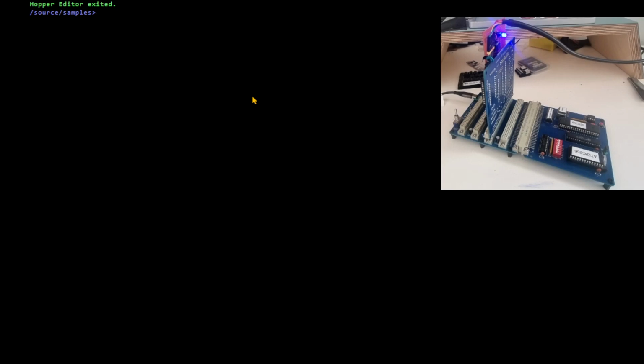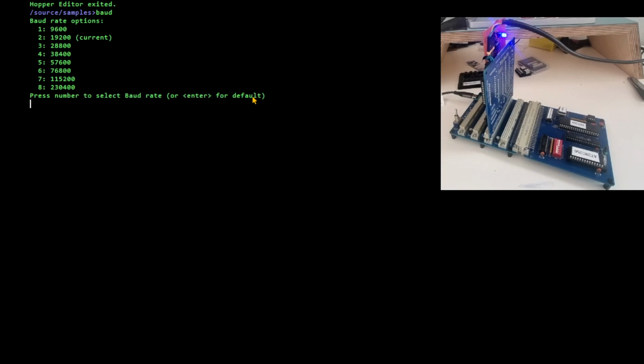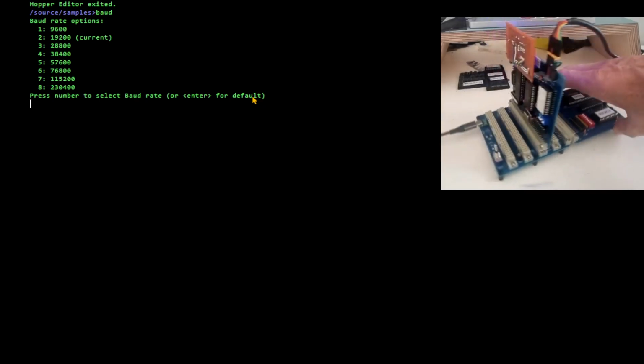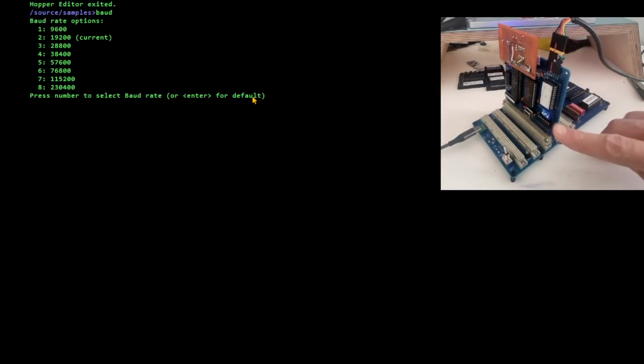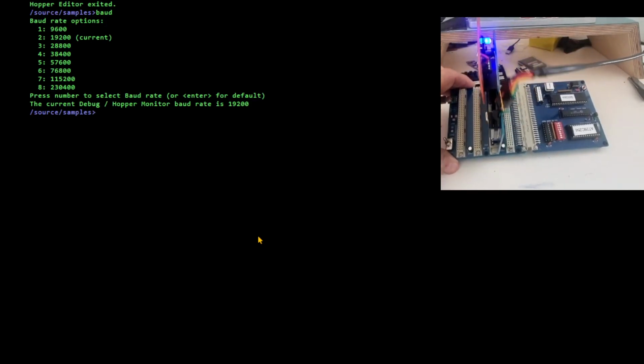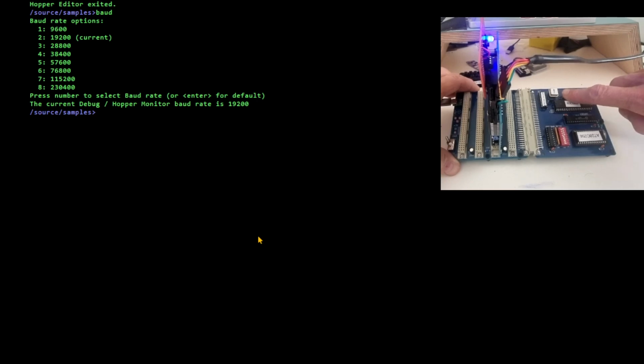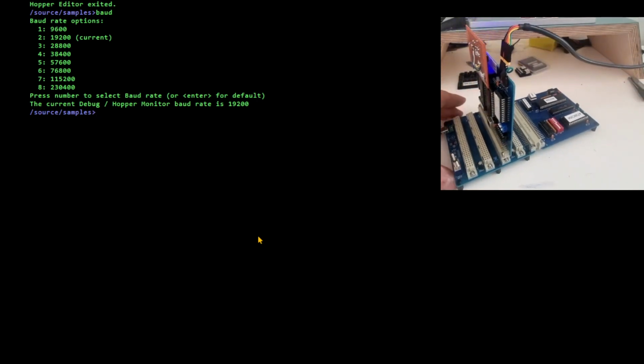Oh yeah, important: baud rate. We've got the board switched, with these dip switches here, the blue one, to 19200. If you're using the Hopper 8K BIOS you can use 76800, but for Hopper itself, 19200, because it doesn't support the XON/XOFF protocol. So you might swap to a serial port. If you run it at 19200, the default on here is a 4 megahertz CPU, and at 4 megahertz 19200 it can keep up just fine.